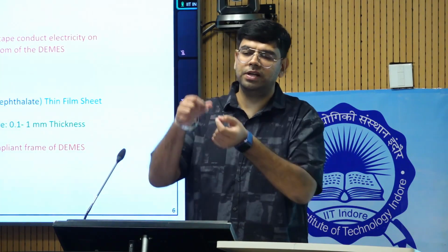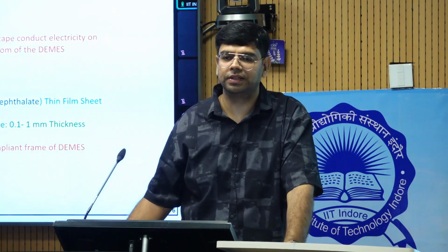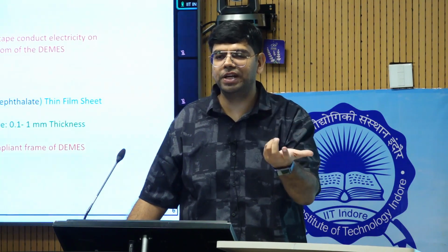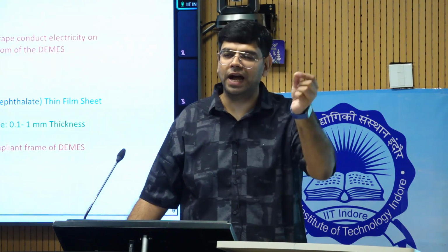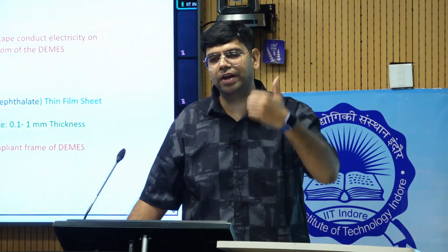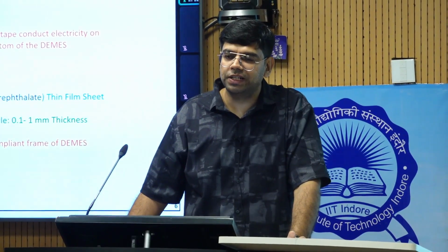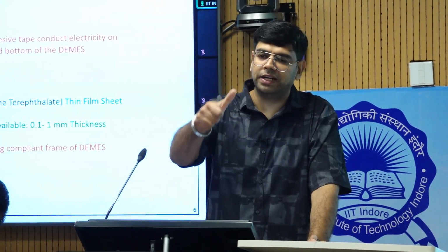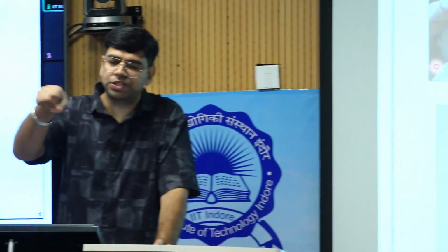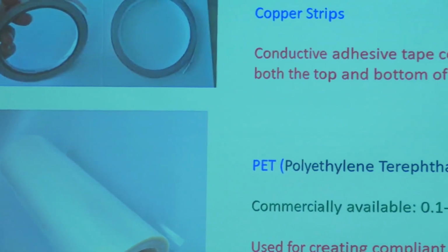When you remove one of the layers, it will stick to the surface. Since our VHB tape has adhesive property, even over the carbon grease it still possesses the adhesive property. When you put it, you need only to press it. And one more thing, for a proper connection, always paint over the copper strip in the active area again. If you don't paint it, there is a very high chance of current leakage from that location.